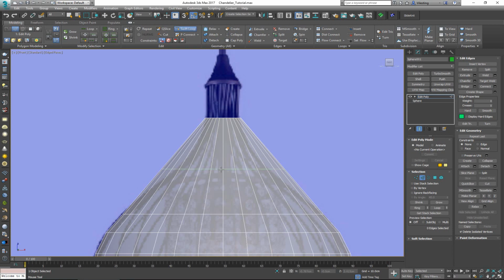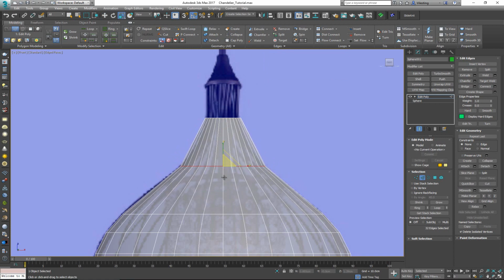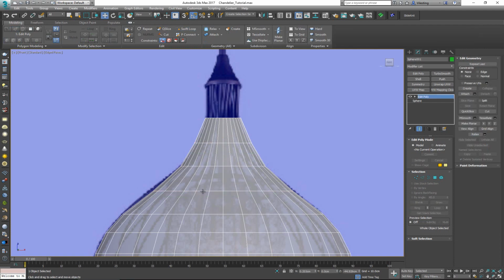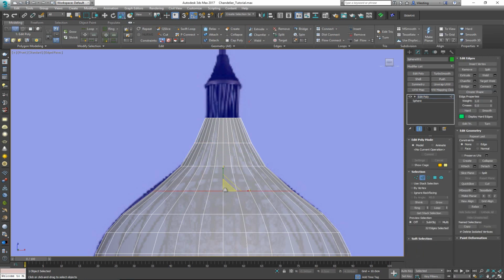But if you hold down Shift, in that case, you're going to add that loop with a set flow applied to it. But in this case, since this was a straight line, we didn't get this tightening, but you're going to notice that here, because once I press Shift and click, I'm going to get this thing to conform better. But since we can go in and manually fix this like so, there we go.